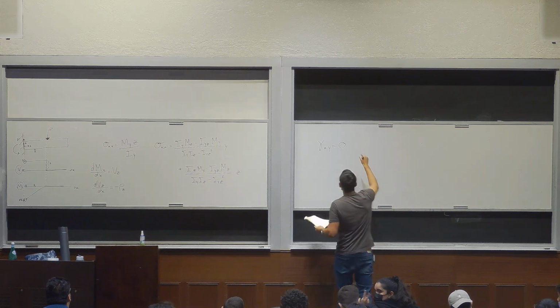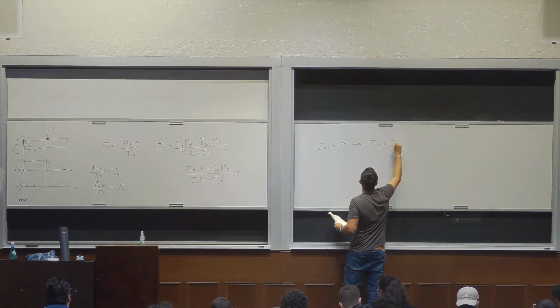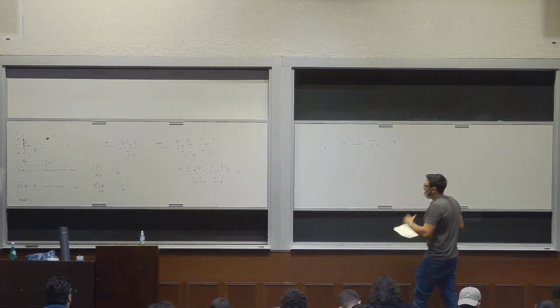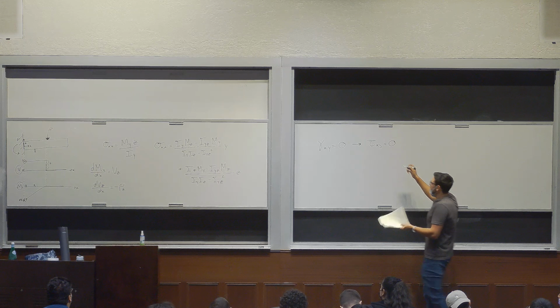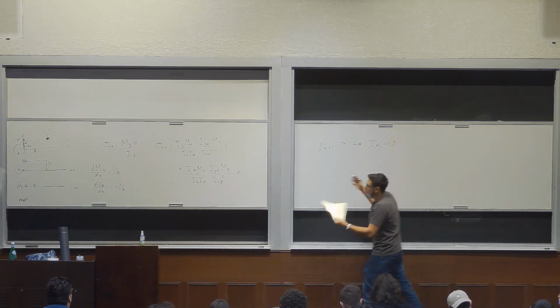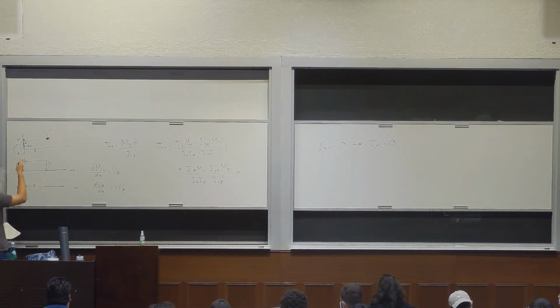And if that's the case, then that results in tau xy equals 0. And that's the contradiction of the Euler-Bernoulli beam theory, because this is not 0, because we know for sure that there is some shear force at a given cross section.